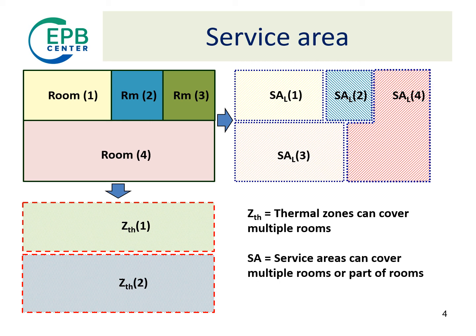For the calculation of the overall energy performance, combine as much as possible spaces into a single service area. Default rules are given when and where partitions are needed, but they can be replaced by national rules. The same goes for other service areas, for heating, cooling, ventilation, etc. Each of the divisions is separate from the other. This has a big advantage. If you have a refined partition for one service, you can still keep the division for all other services simple.